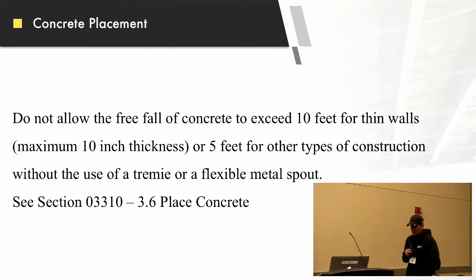It's very important to make sure you trim your concrete, because if you just start dumping it in, not only are you dropping it too far, but you're hitting all that rebar that's in there, and the segregation is just incredible. And so you're not going to get a good, cohesive, consistent mix down throughout your entire placement.